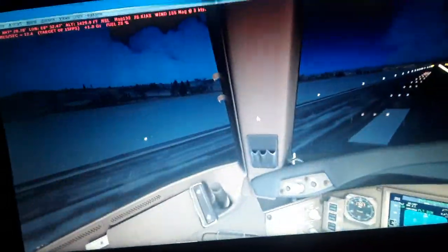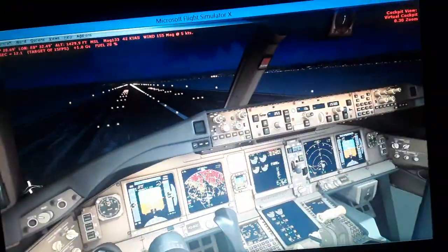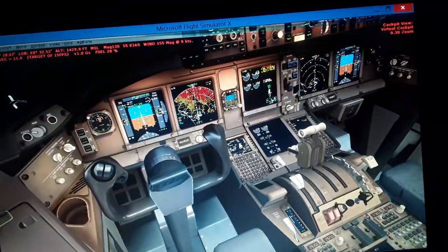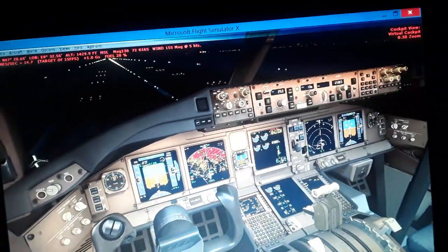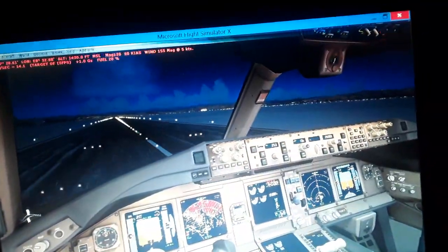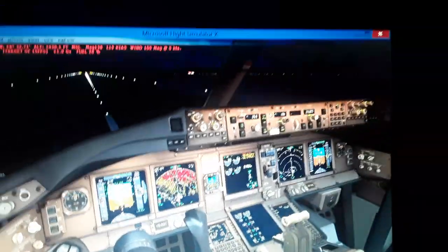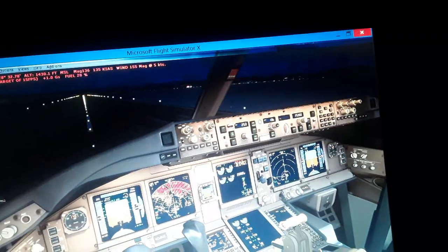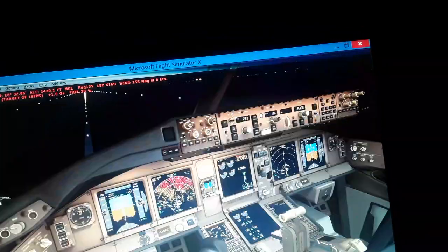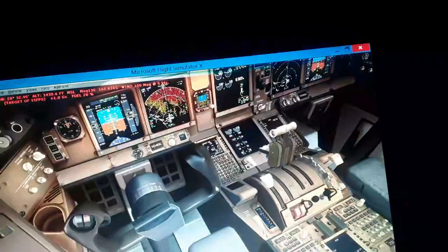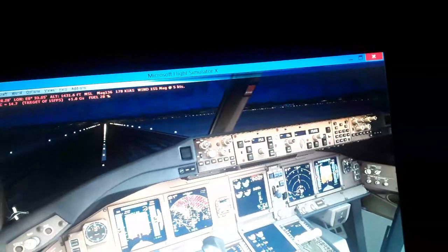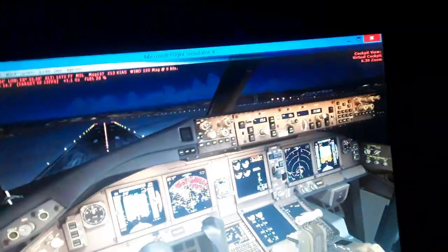So when we reach the V1, we rotate, align with the rudder pedals here on the steering. So we have a few more minutes to go. V1, we rotate. You can pitch up like this. So we have the rotation speed here. Be careful not to hit the tail of the airplane as we climb.